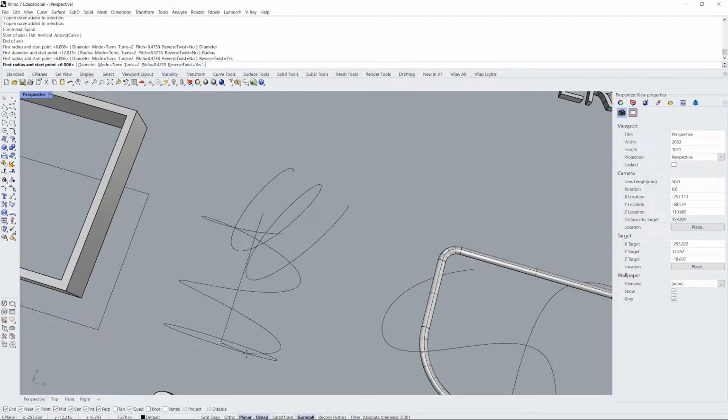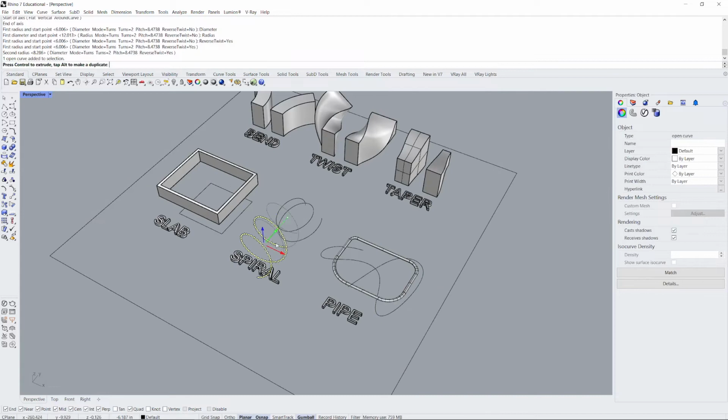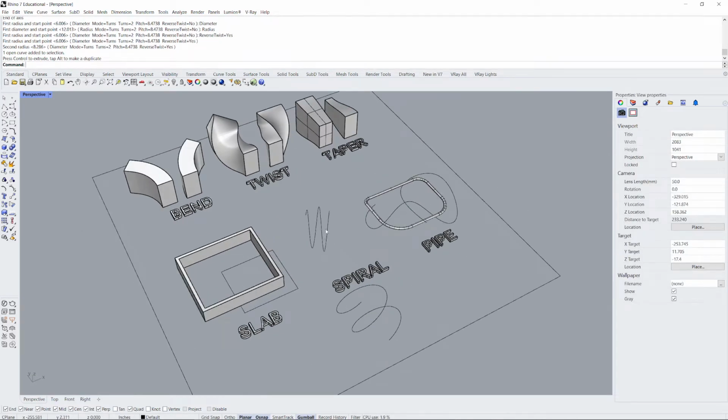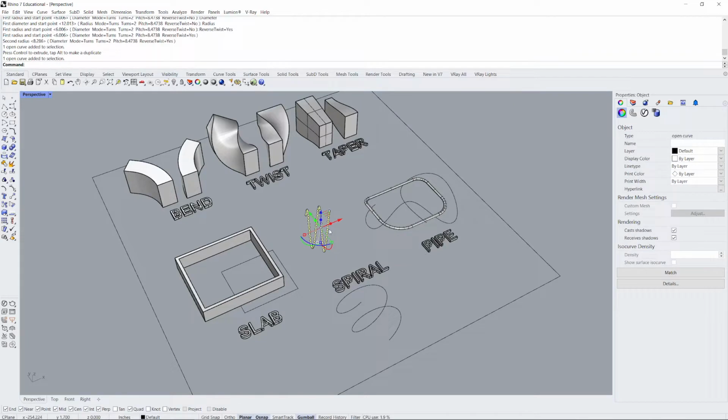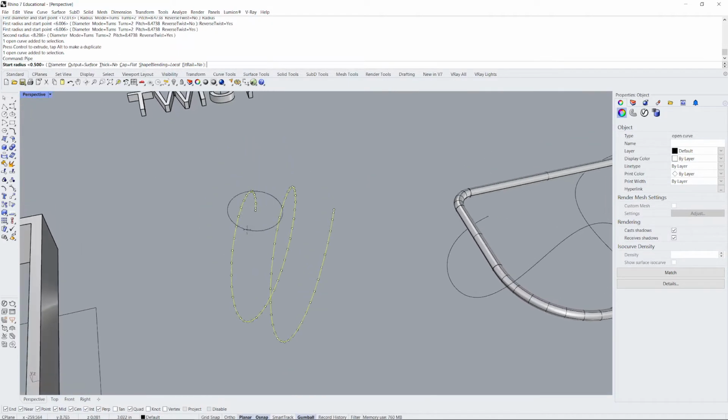This is really useful in situations where you're trying to replicate something like a spring or a pigtail of some kind. What's really great is now you can select something like that, and you can use this next command, pipe. What it does is it creates a solid tube. You do want to, as with everything, check these command prompts up here.